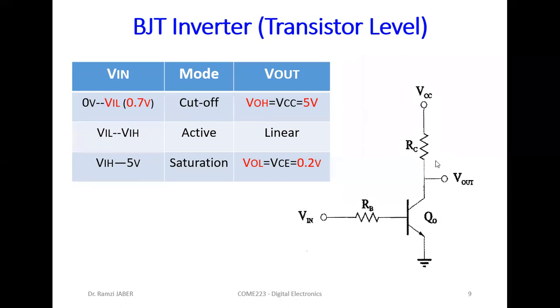Okay, that's why we must put a resistor. Resistors on C, on B, later on E. But on one of them we can put ground. Ground doesn't burn it, it doesn't affect anything on the transistor. But if we put 5 volt here or here directly, the transistor will burn out. So we put a resistor. This resistor is called, for the side of the collector C, RC. This is B, base, RB, and this is E. Okay, so we put two resistors, RC and RB.